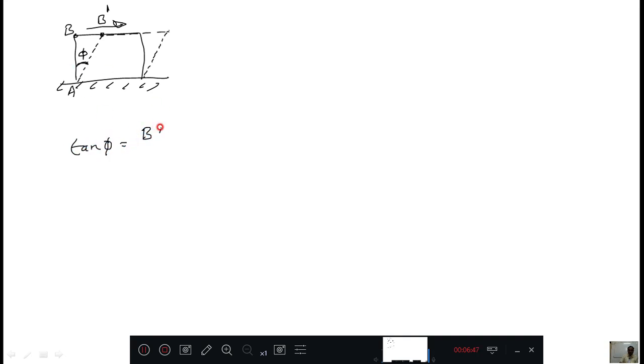Now, when we apply this, how does the body behave? When I apply the force here, the body will deviate in this direction, because the bottom is fixed. Then I observe a change in angle, which I call phi. If this is a and this is b, and b slides to b dash, then tan phi equals opposite by adjacent, which is b dash divided by ab.